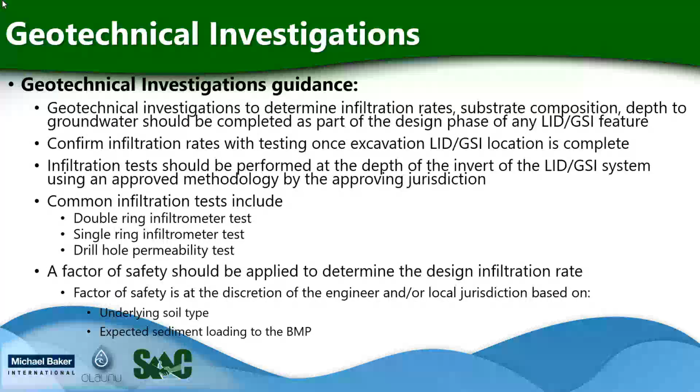Confirmation of infiltration rates with testing once excavation of the GSI LID location is complete is a critical step to confirming that the infiltration rates are actually going to work for the design storm. Infiltration tests should be performed at the depth of the invert of the LID GSI system using an appropriate methodology by the approving jurisdiction. Common infiltration tests include double ring infiltrometer test, single ring infiltrometer test, and drill hole permeability test.